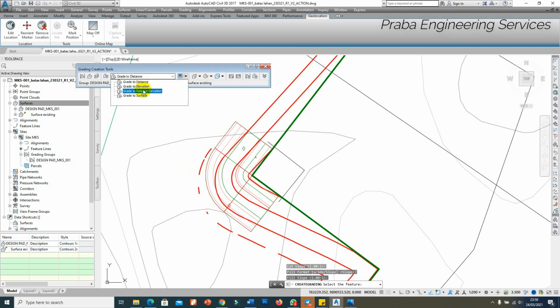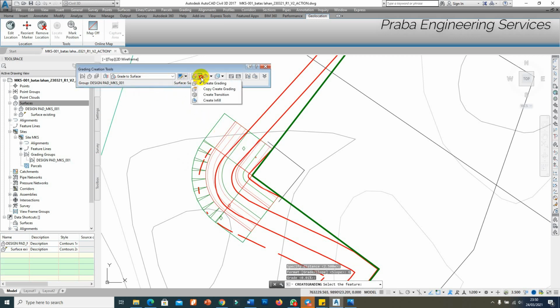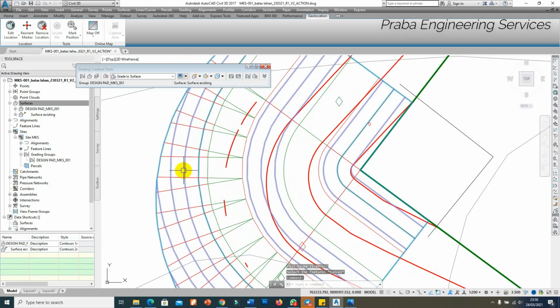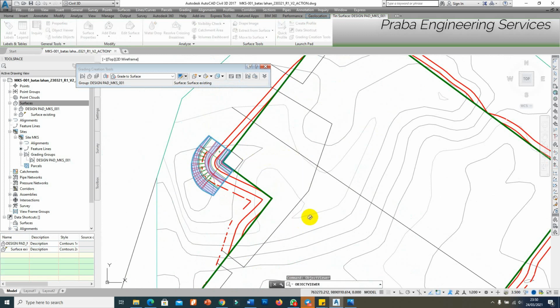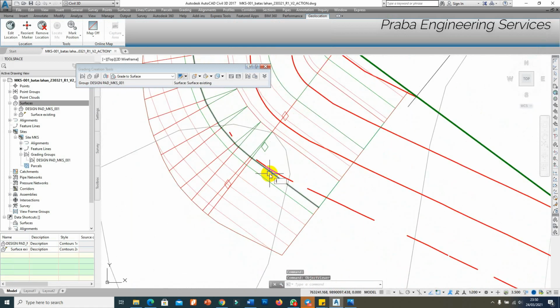Okay, then go to distance, distance again, apply to entire line, yes, specify distance, yes, choose grade. Then grade already, and the last is go to surface, grade surface, apply to entire length, slope 1 by 1, slope 1 by 1. Okay, perfect. This is the location. If there are still more than 3 meters, we need to modify. We can check by ID.